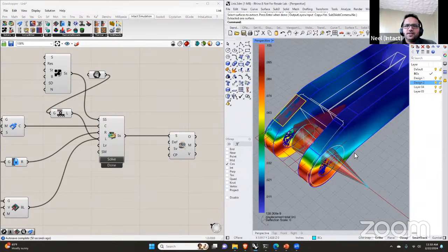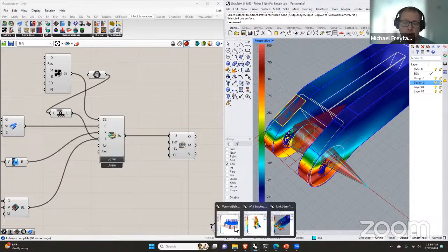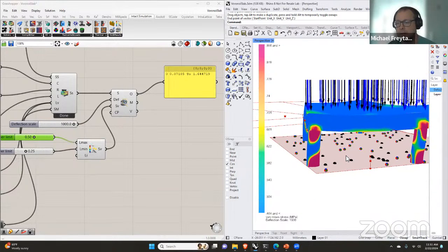Cool, thanks. And in general, we support bonded joints, right? Like for multi-material assemblies. That's a good point. Anywhere you have multiple components, for example this one, these are separate solids. The columns are separate solids. The slab is a separate solid, but anywhere they're in contact is basically treated as bonded.